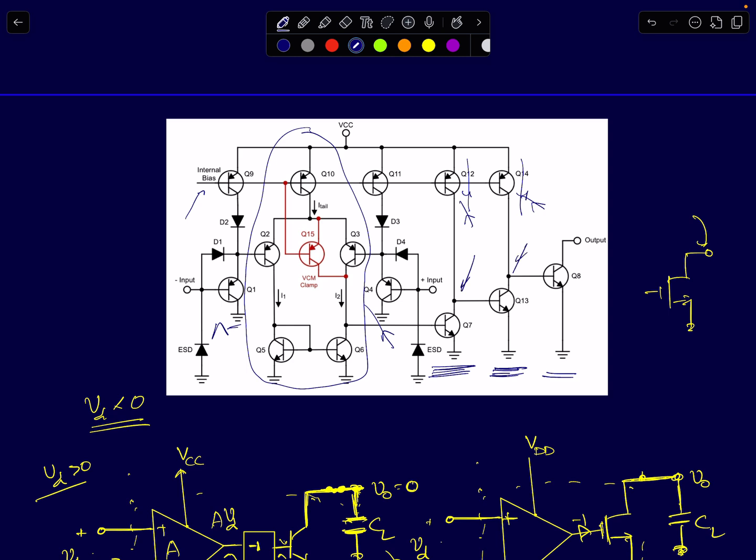If you look at the final output stage, the output of this final common emitter amplifier is floating. It's open. So when you look at the circuit schematic, you will see the final stage is open. That's called an open collector output comparator. So when you see the term open collector output in the data sheet, you should picture that the last stage collector terminal is floating. If this comparator was realized using MOSFETs, the last stage would be a common source amplifier with an open drain output.